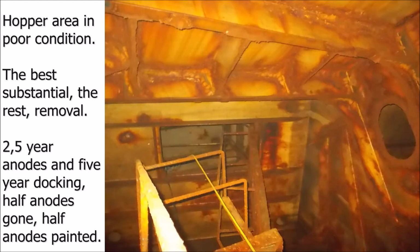The problem here was anodes for 2.5 years and 5-year dockings. Half of those anodes, they were gone, of course. And the other half of them, they were like new, brand new, with tape all over them. So that is a reason for this very bad condition. So you make sure that the tape used to cover those anodes is gone when you leave the dockyard, and that you have the right system, the 5-year system.